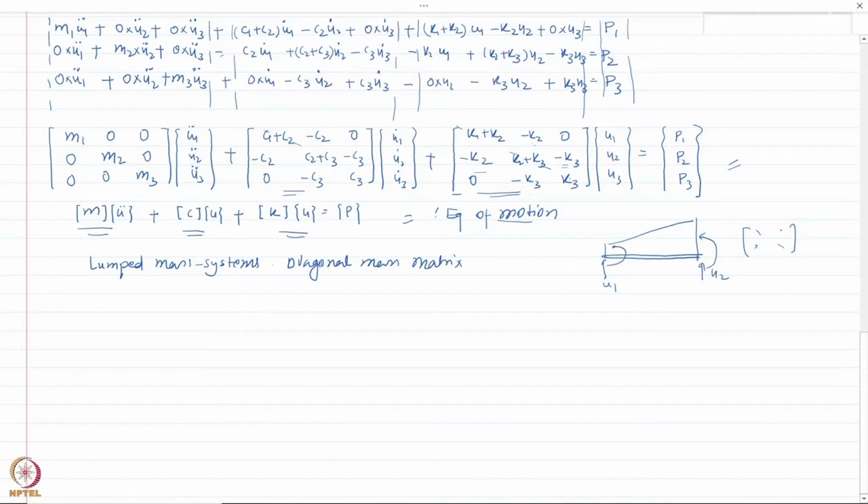And the third observation is that if we define our damping matrix, or the dampers, in such a way that it represents the same degrees of freedom to which the stiffnesses have been defined, then the form of the damping matrix would be the same as the stiffness matrix. This is especially true for a multi-story building in which dampers are defined at each story.